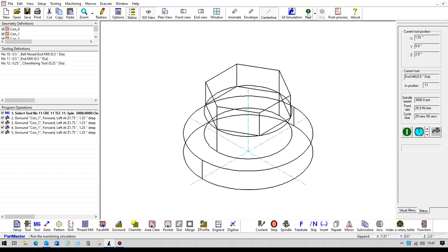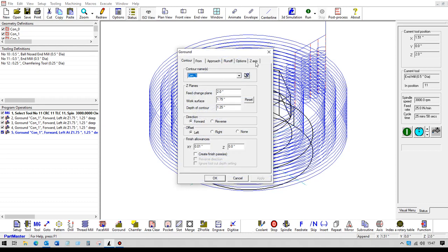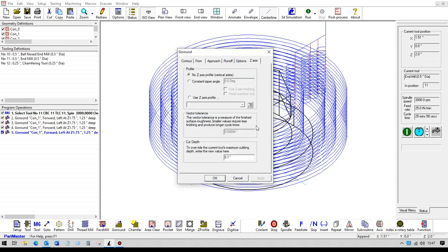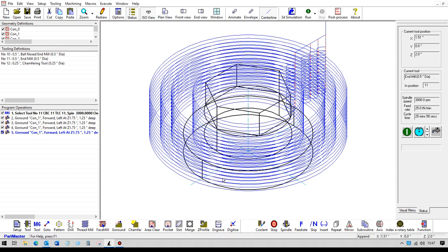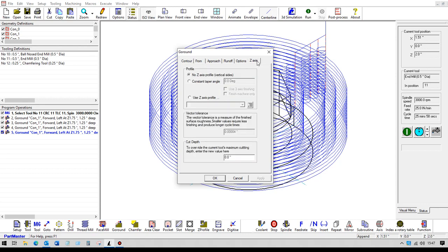Okay, so that's produced multiple setups there. But the last one, if this is a finishing pass, then you can set the cut depth the same as before, but that will leave on that amount of material, so we need to produce another go round command, and that was on con 1. We'll have no offset and no step down in the Z axis.